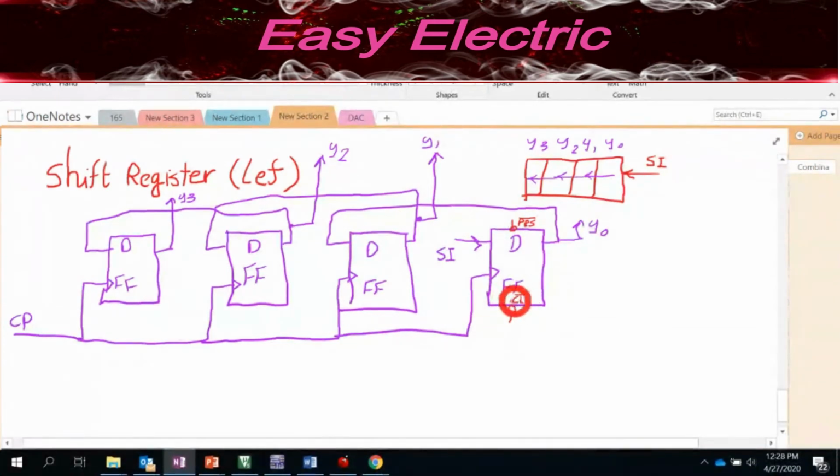So if you activate the clear, the output will be 0 no matter what you have as input on the flip-flop. If you activate this, the output is 1 no matter what you have on the clock and your inputs. So we usually have one initialize input, we say INT bar, which is where we connect all of these